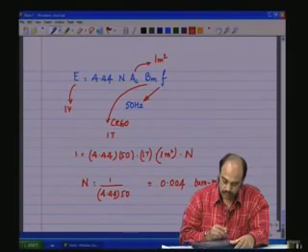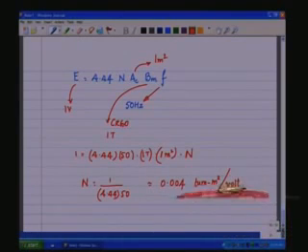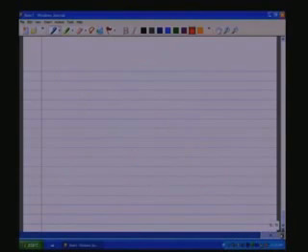This is for 1 volt, so many turns for 1 volt, and the area comes in, so that is the meter square per volt. This would be an approximate thumb rule which will give you at least a figure of what will be the order of magnitude of the turns that you would be applying. So, N is equal to 0.004 turns meter square per volt.